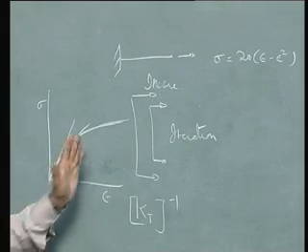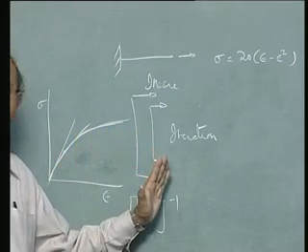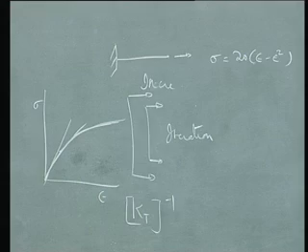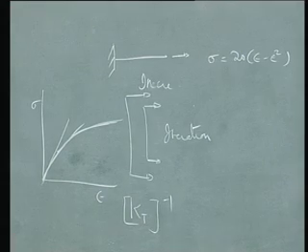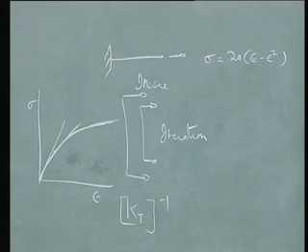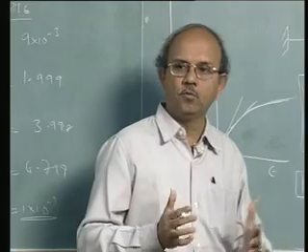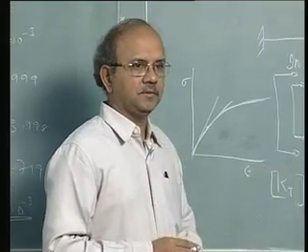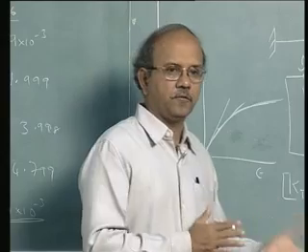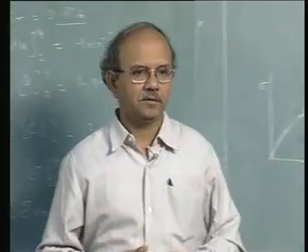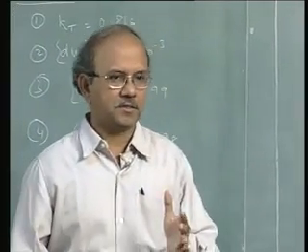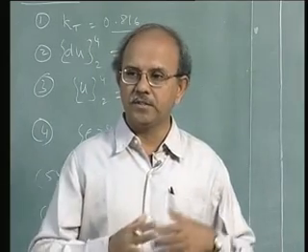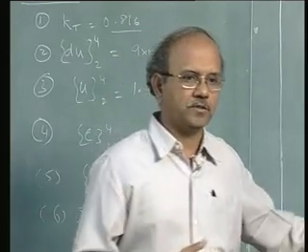But of course, I'm not saying that every problem will end up in a situation where you can't solve. It would so happen that thankfully when we have a lot of elements and when the deformations are inhomogeneous, somehow Kt would still keep going. In other words, when deformations are not the same at every point, the stiffness matrices that are formed due to these elements would be such that it would be better than what we are seeing.